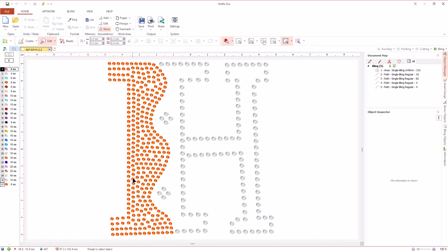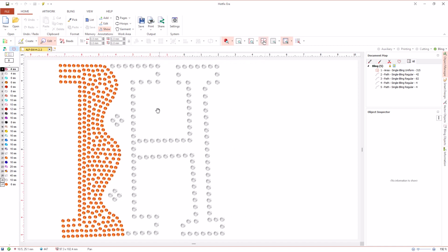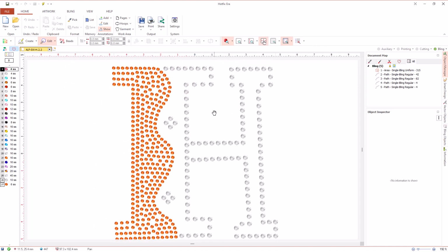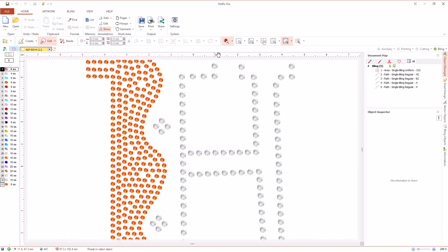The view will zoom promptly. The pan function, to move the point of view of the design, is also available in the toolbar. However, again, if our mouse has a wheel with a button, we just need to press the wheel and drag to pan the design easily. An alternative way to pan is to place the mouse pointer over the rulers and drag.